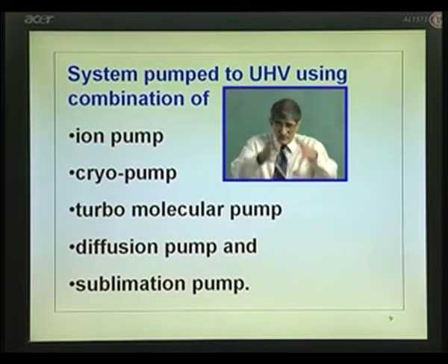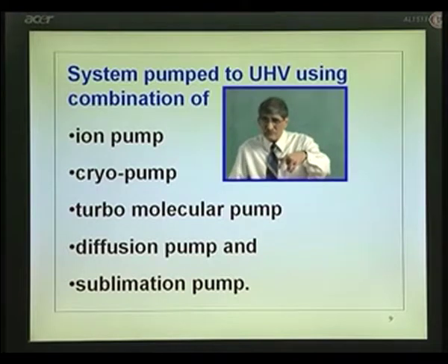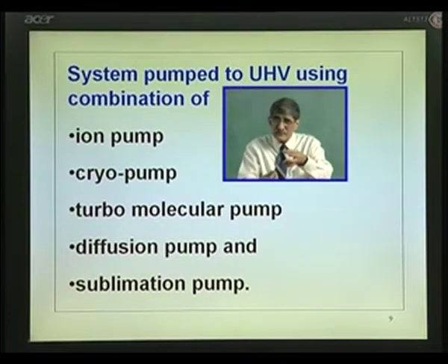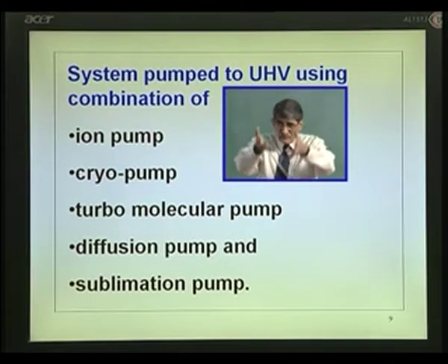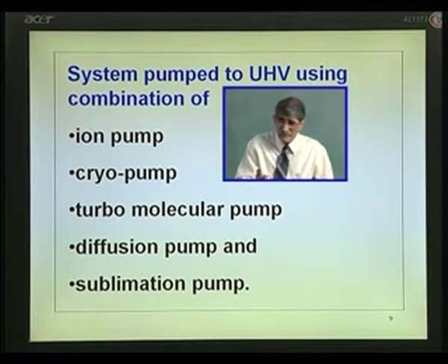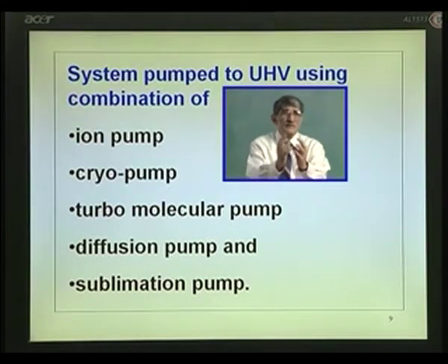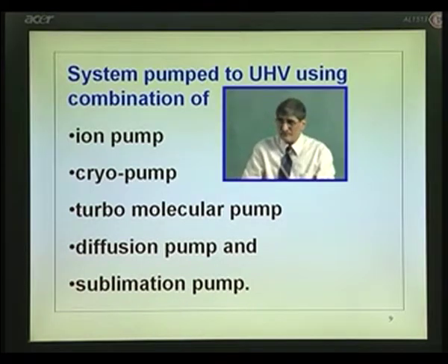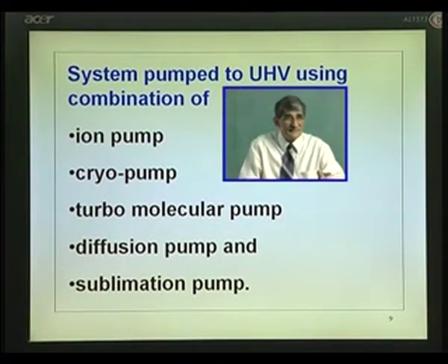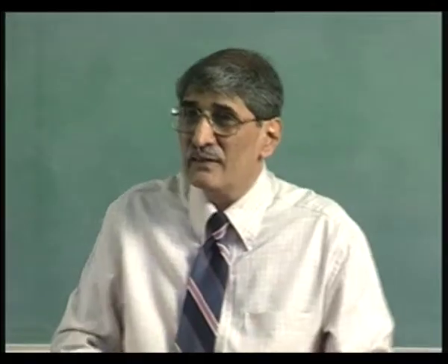You connect it to a system which is pumped down, and as you create lower pressure here, the molecules will diffuse from the chamber down to this pumping system. That is why those pumps are called diffusion pumps. Let me not get into more details of that. In fact, you will have a heater which will pump oil into the top, that will collect the molecules and bring them down. So, to prevent the oil from entering into the chamber, you will have a liquid nitrogen trap, so that the oil vapors do not go back into the system. That blocks it.